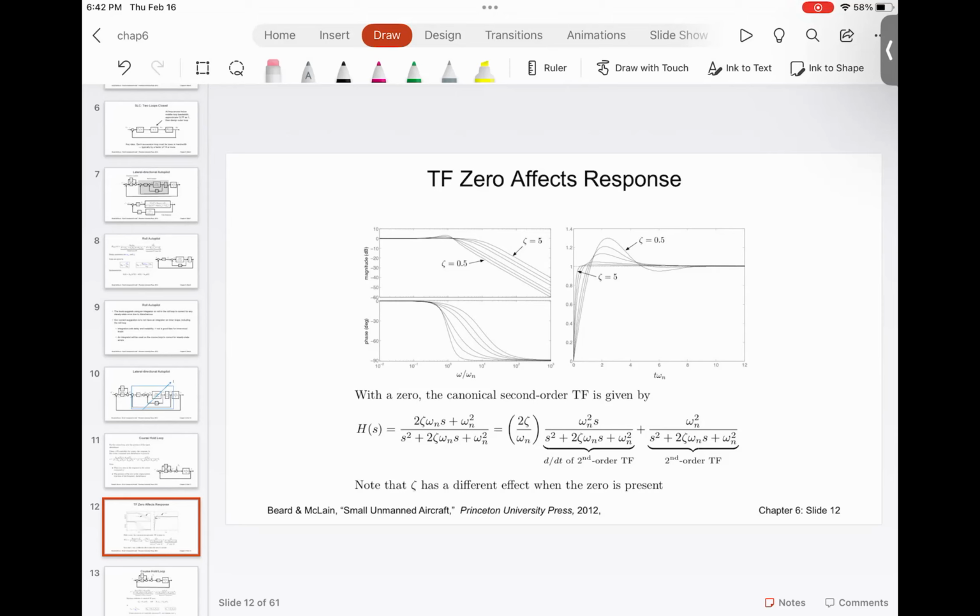What is this Bode plot telling me? The Bode plot is telling me, as I sweep the frequency from 0 to very high frequency, how the system is going to behave. As I can see, it has 0 magnitude initially, and then the magnitude kind of goes down. So as the damping coefficient increases, the system response dampens.